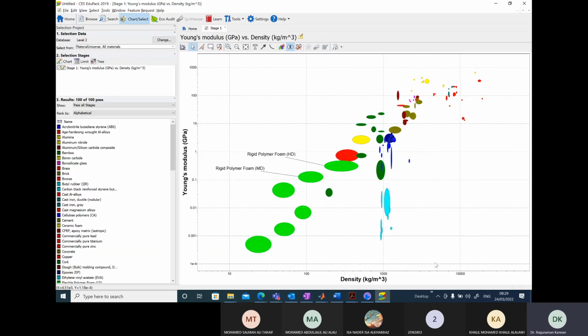You can pick any point, for example, 10,000 here. I want to draw a guideline from the 10,000 point. So how would I draw that? I choose 10,000. In the rho axis, I move 2 divisions, 1, 2. So if I move 2 divisions on the rho axis, on the y-axis I will move 1 division.